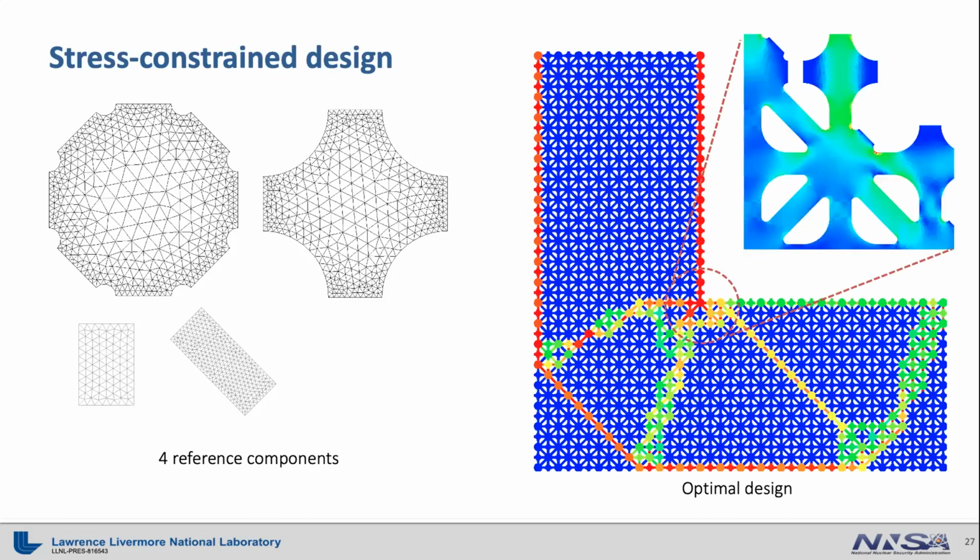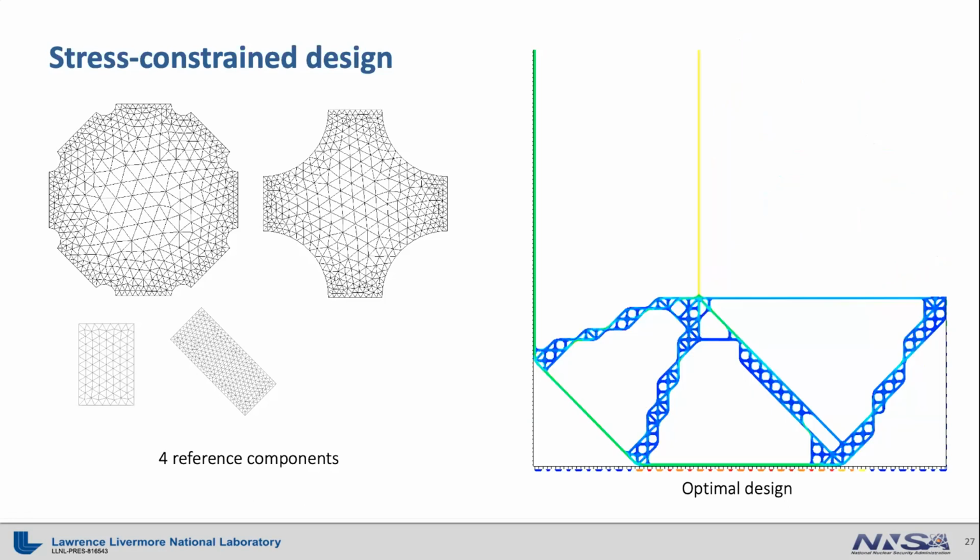Here is the zoomed-in picture of components in the optimal design with very detailed stress control plots, which you cannot get with other types of lattice structure design methods. Finally, we can post-process the design to get rid of all the hanging structures to make it pretty and manufacturable.